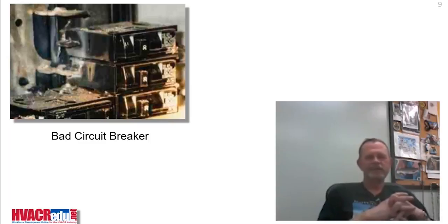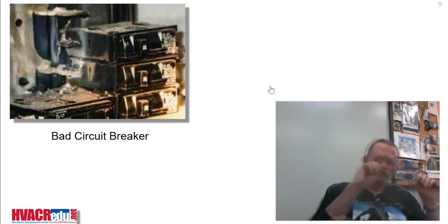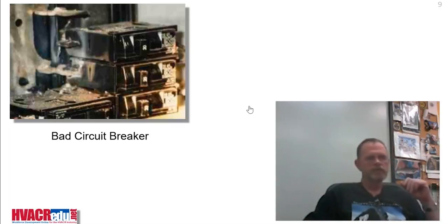All right. Okay, Jimmy. Glad you're new to this because you're here learning. Good for you. So I just want to emphasize, a circuit breaker is a switch. A circuit breaker can develop a voltage drop internal to the circuit breaker. My demonstration in the webinar two weeks ago was to take the back of your hand and run down those circuit breakers in the panel. When you find a warm one, my next recommendation would be to measure across that circuit breaker from power in to power out and see if you have a voltage drop. If you have a voltage drop, you can probably expect it's a circuit breaker.